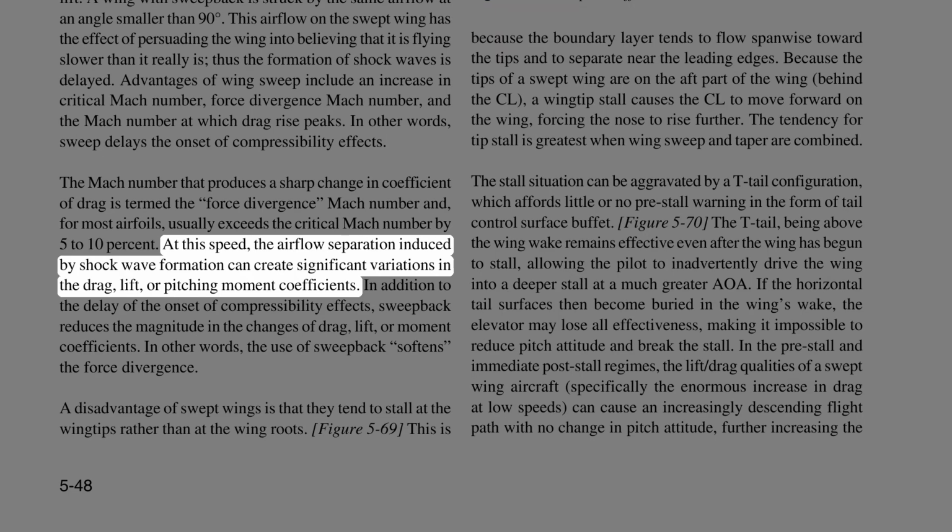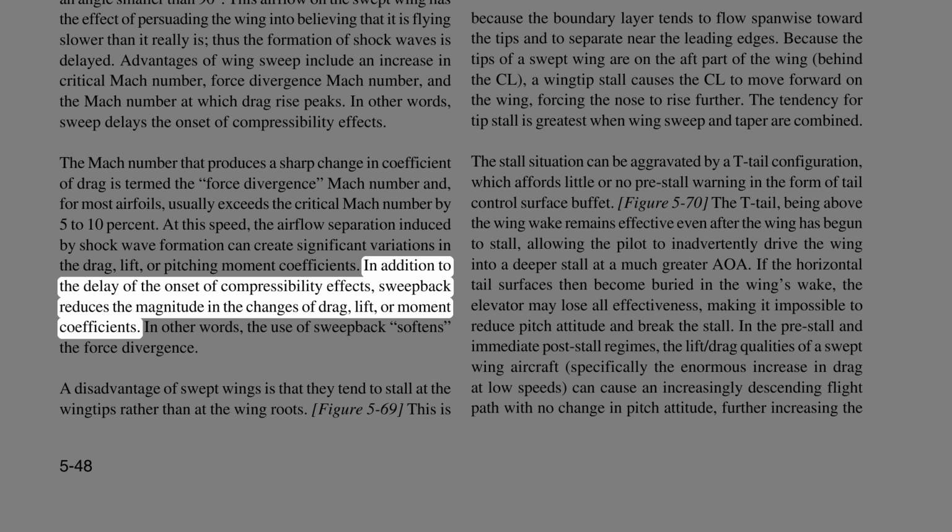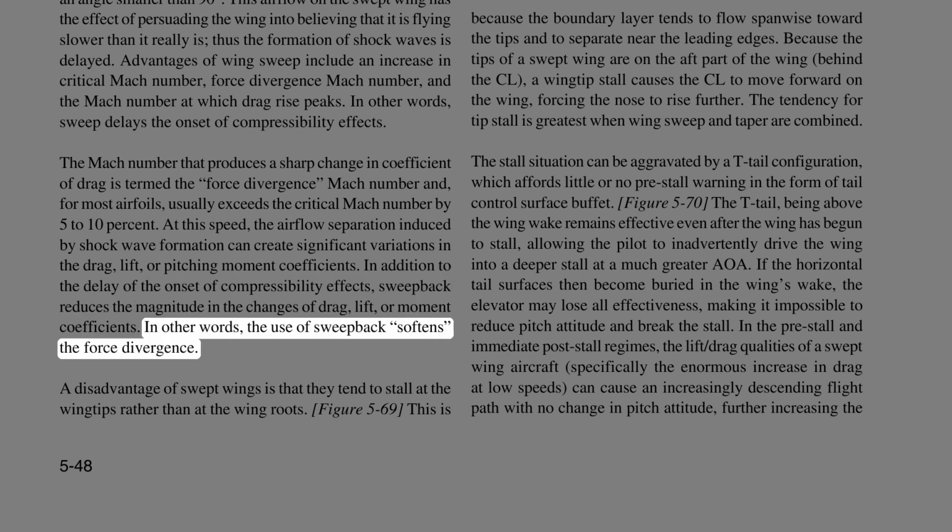At this speed, the airflow separation induced by shockwave formation can create significant variations in the drag, lift, or pitching moment coefficients. In addition to the delay of the onset of compressibility effects, sweepback reduces the magnitude in the changes of drag, lift, or moment coefficients. In other words, the use of sweepback softens the force divergence.